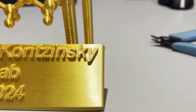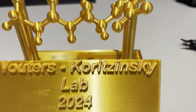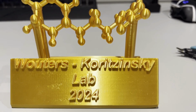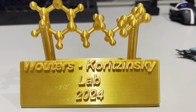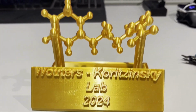There's a nice gold sheen, which actually gets more and more visible the thinner layer heights become. But for the sake of print time, this was a 0.2 millimeter layer height, printing for about 1 day, 3 hours. So again, if we were to do, say, 0.1 millimeter layer height, double time, same amount of plastic, but 2 days.